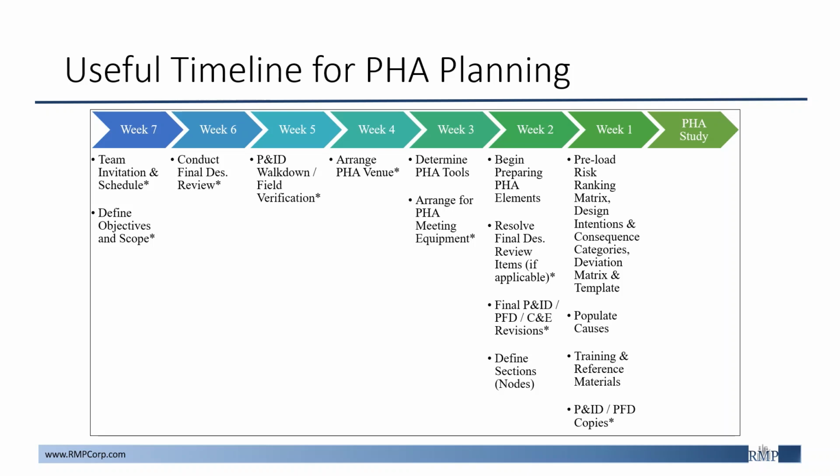After the final design is reviewed, it is important for personnel to perform a P&ID walkdown to verify that the drawings accurately represent what is in the field. This is important to be done early, as the time spent during the HAZOP sessions should not be filled with field verification due to team members seeing a discrepancy on the P&ID compared to what they have seen in the field. With the proper walkdown, this can help ensure that the P&IDs are drafted correctly.